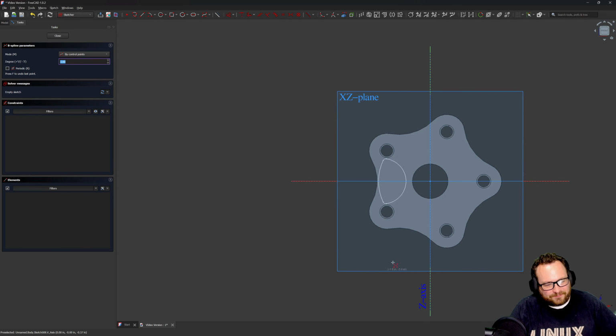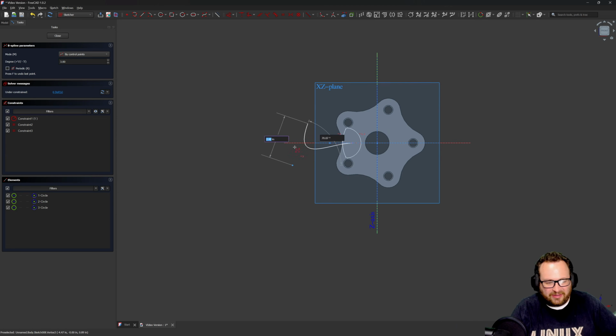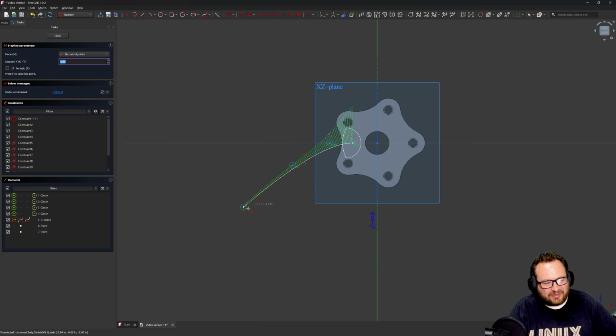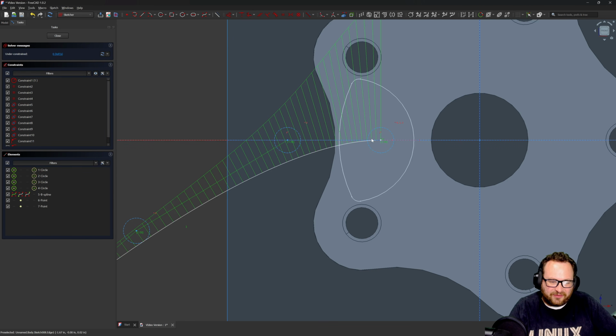For that, I'm going to create a spline here, a B-spline. We're going to have the first 2 points on that horizontal sketch axis and maybe 2 more points. Right, so it proceeds out with a nice non-constant radius. And then I have the first 2 points on this axis, which means that no matter what this curvature is, this endpoint is always tangent to horizontal.